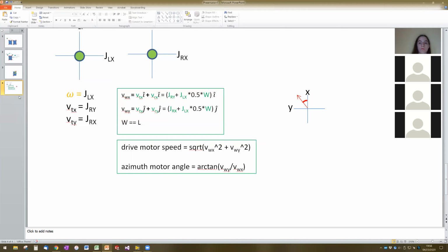So what we did was we put all of the outputs, like we got the extra big number, and we put it in an array, and then we figured out the maximum, and then we divided all of the numbers by the maximum. So whatever the max was changed to 1, like if it was over 1. So exactly. So we've got 4 drive motor speeds at any given time, 1 for each module.